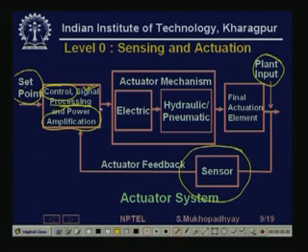Now in an actuator so much power amplification is necessary that it is always done in stages. First there is one level of power amplification at the electrical level: you take one electrical signal and increase its electrical power. But if you want to increase power further, often we go to different forms of energy. If we have a motor driven actuator, sometimes it is driven directly from the power amplifier, or sometimes it may be driven using hydraulic or pneumatic devices.